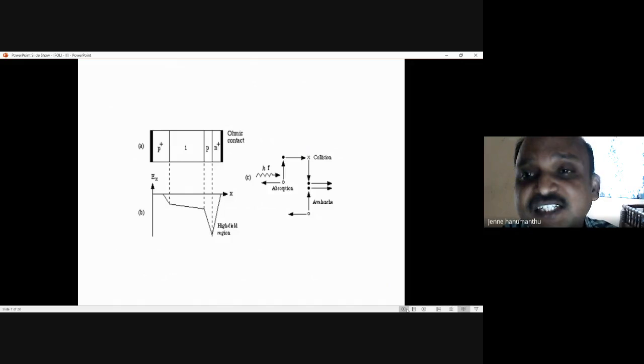It is also one more PN junction. We applied a large reverse bias, so at this junction between P and N plus, there exists a large reverse bias. Because of the additional P layer in conjunction with the N plus layer, it creates another PN junction, which is already excited by the large reverse bias. Remember, this is the point.